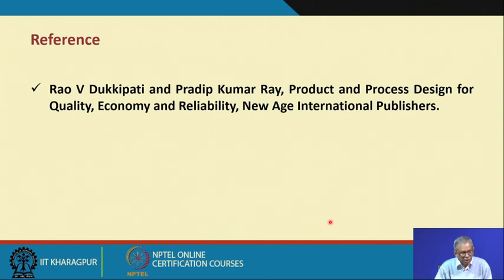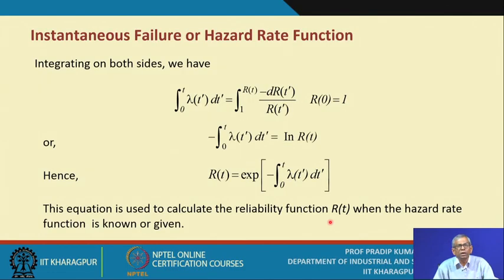Now here is one important issue I should highlight. The MTTF is definitely one of the measures for assessing reliability, but another measure we also often refer to is MTBF, which is essentially the mean time between failures. MTTF and MTBF are two different terms, but under certain conditions MTTF may be approximated as MTBF.